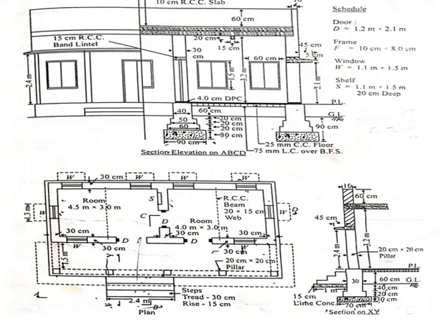Now in this question we also have the veranda, so let us try to find out the center to center length of the front long wall of the veranda, that is this portion. Now how will we calculate it? Simply we will add half the thickness of this wall plus this length plus half the thickness of this wall.